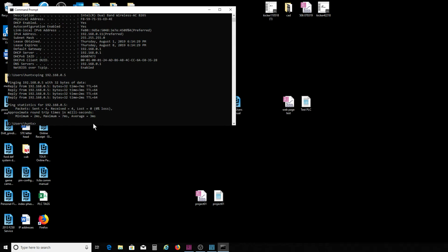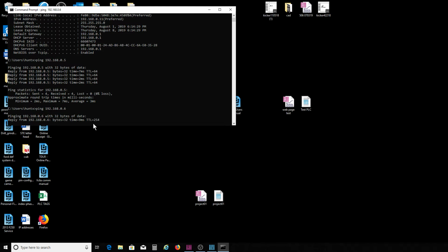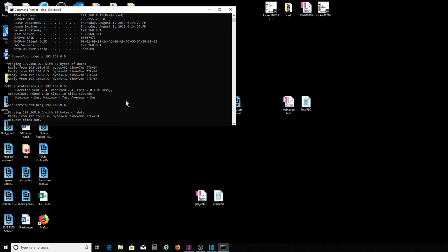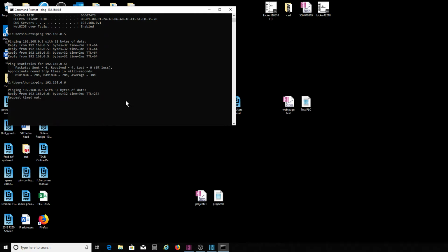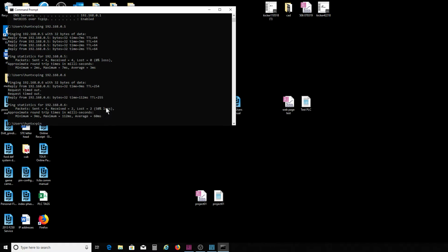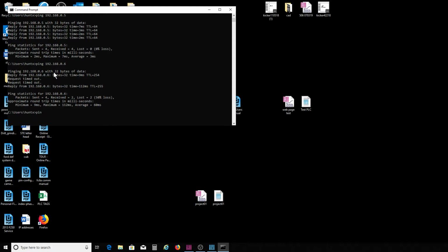All right, let's ping my HMI. Just to show you how to do it again. Ping space 192.168.0.6. Okay, there's my HMI. Oops, for some reason I got a request timeout on that one. Let's try it again. Oh, there it goes. It did it after that.